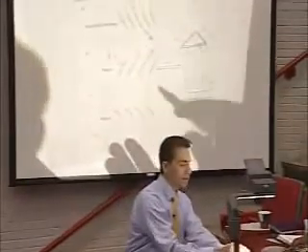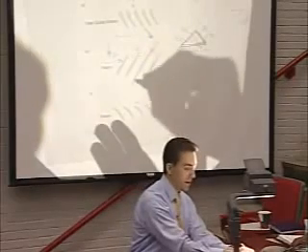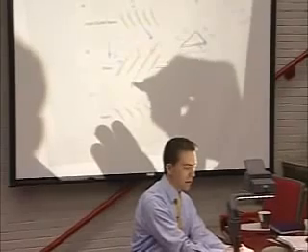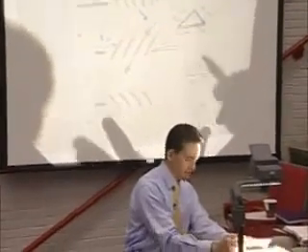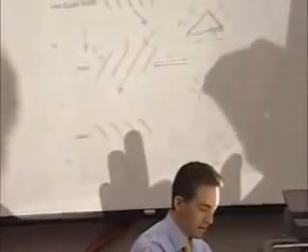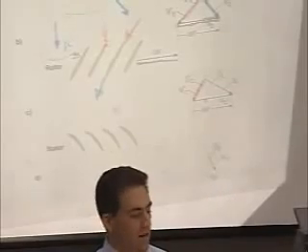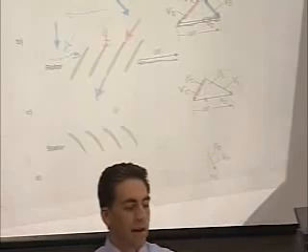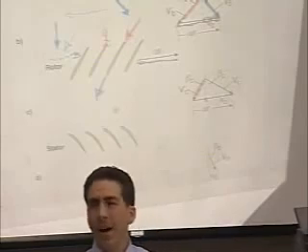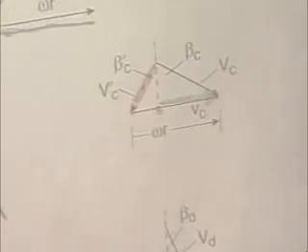In the reference frame of this blade now, you assume that it leaves at the flow angle, or at the trailing edge angle. That is this, which I keep drawing in red to stay consistent over here. So that's the flow angle leaving these blades. And now, what I really care about again is this component in the stationary frame.